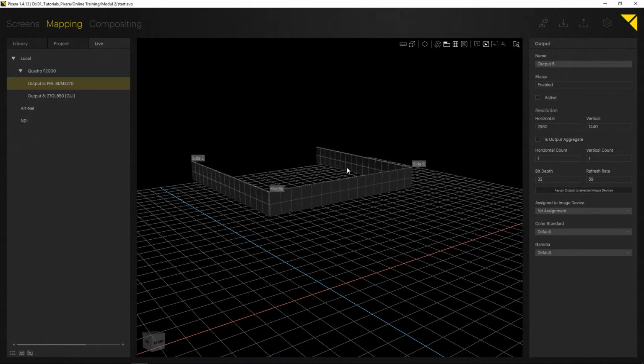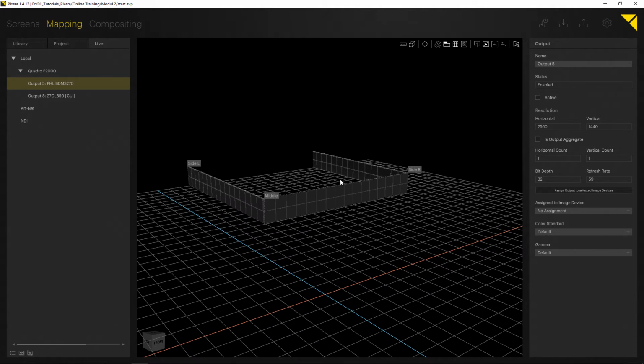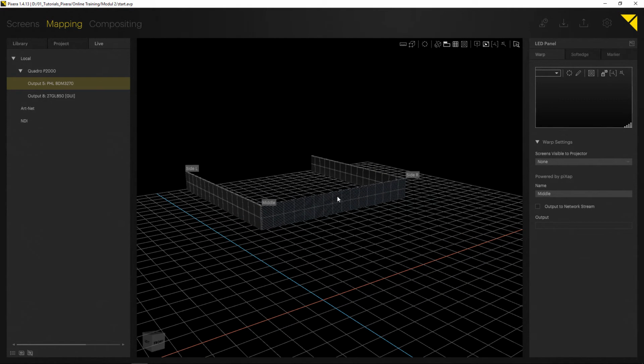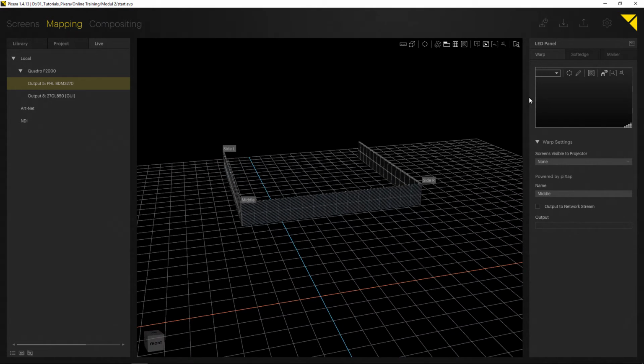Now we somehow have to connect our output to our 3 LEDs. And in order to do so, the first thing you want to do is check that screen selection is activated in here. If it is at projectors, as you can see, I cannot select any of the LEDs. So let's go here to screens, and also by pressing Shift and Tab, you can change between the selection. Now I can select my LED. And I now immediately see on my right-hand side some information, especially the outputs.